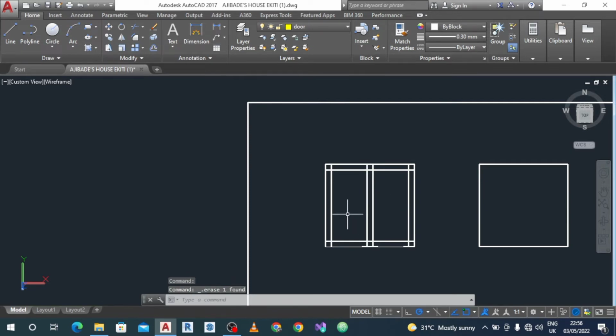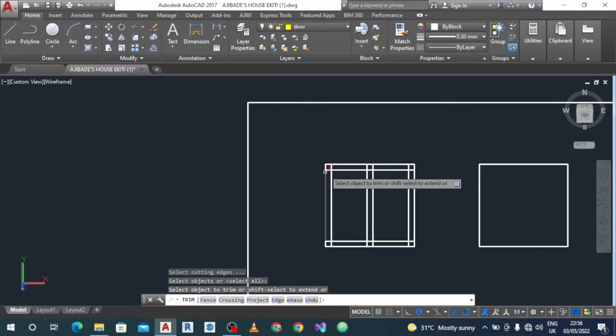and after this we introduce our trim, that is TR, enter. So we take off our corner lines. That's what we want to do. Take off our corner lines is what we want to do. Yeah, so after that, then this inner lines, we take them off.